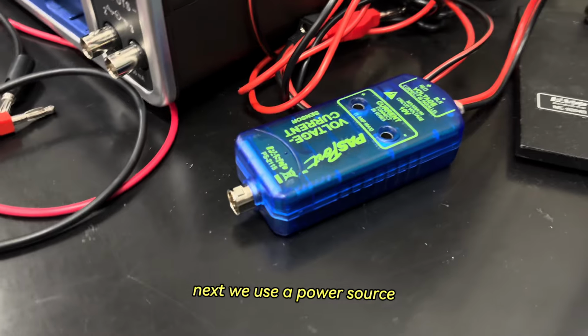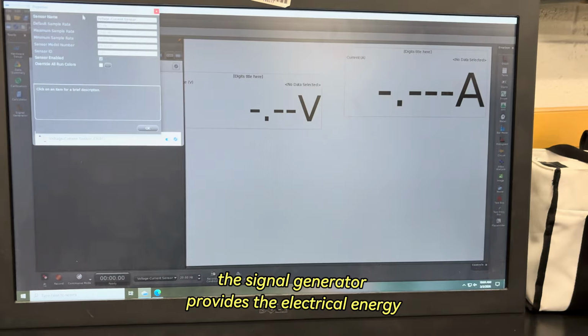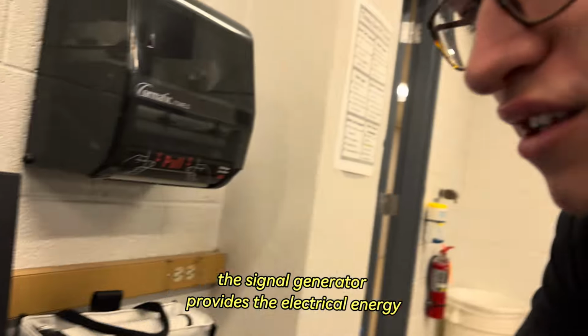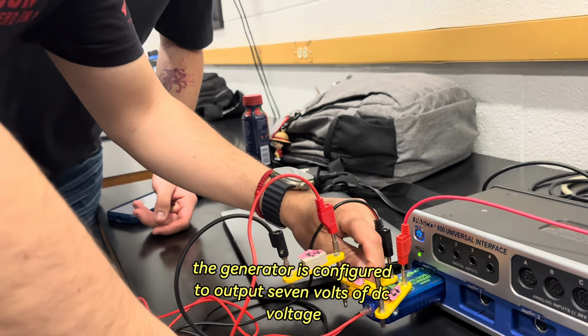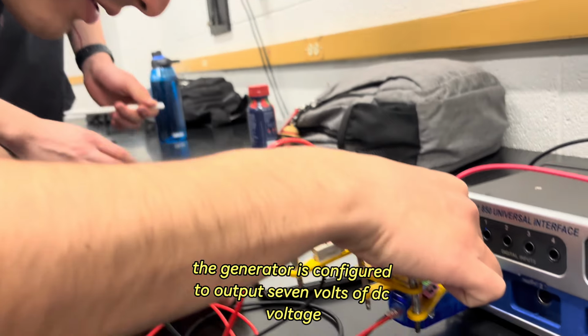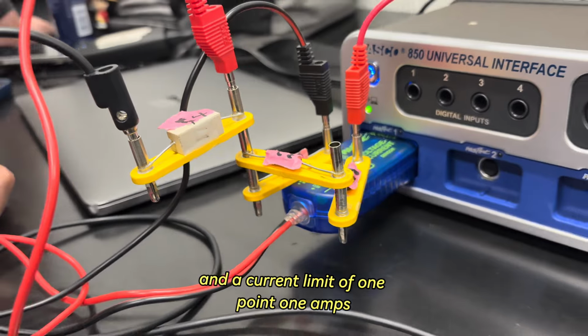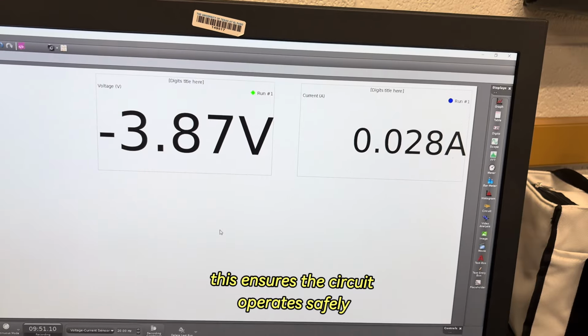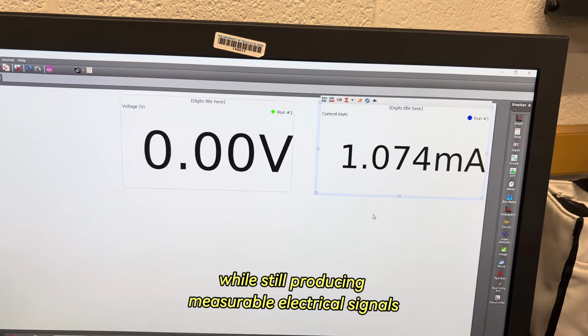Next, we use a power source, specifically a signal generator, set to direct current. The signal generator provides the electrical energy that drives the current through the circuit. For this experiment, the generator is configured to output 7 volts of DC voltage with a voltage limit of 10 volts and a current limit of 1.1 amps. This ensures the circuit operates safely while still producing measurable electrical signals.